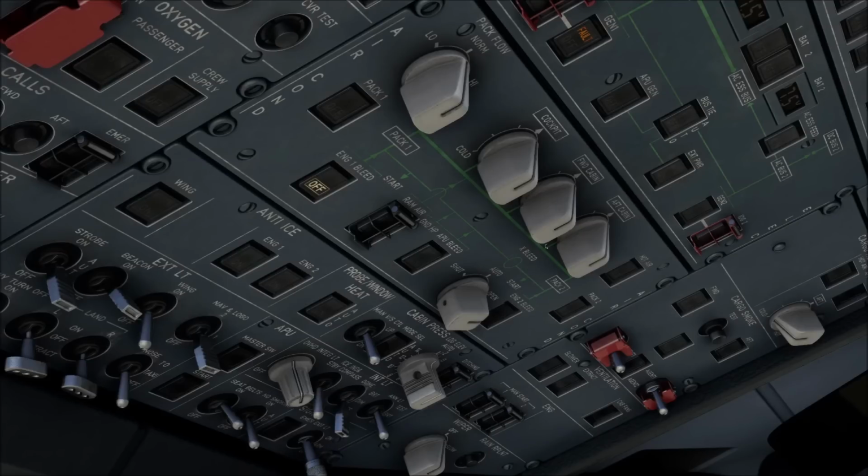So adjust thrust of supplying engine to obtain an engine bleed pressure of 30 psi before start initiation and at least 25 psi during the start sequence. If the thrust required to obtain the appropriate engine bleed pressure exceeds 40% N1, pay particular attention to the surrounding area. And from here on, we are simply going to use normal start procedures.